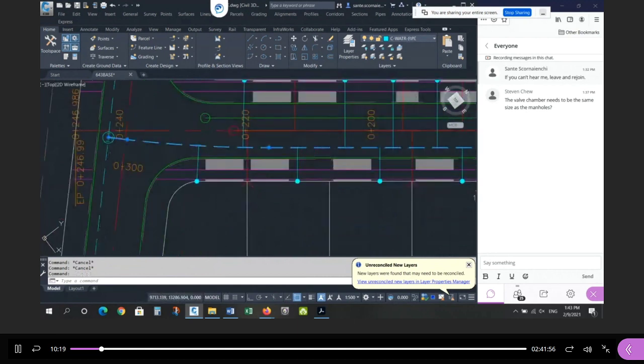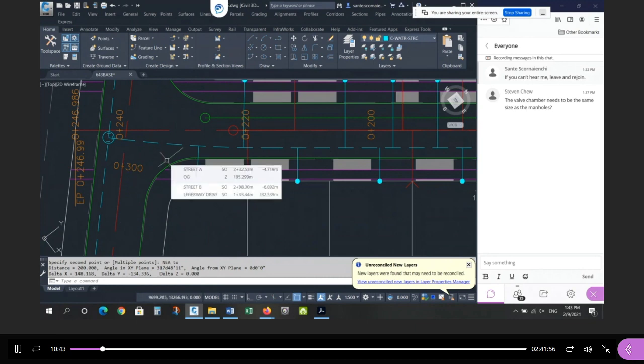So what I did was I took this alignment, the standard position, and I bent the pipe using joint deflection. And I used a radius, and this radius, the distance from the center of this line to a near point on this arc, I'm using a 200-meter radius, okay? Bigger than the recommended minimum. Why? Because I don't want to use a joint deflection of 3%. I want to use a joint deflection of 2%, okay? So why am I using 200?